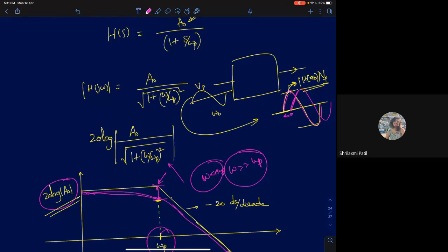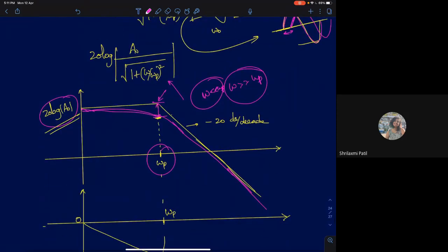And that information about instability, you can understand it by looking at the phase response. So that's where phase response comes in very handy. Magnitude response is very important because that's a fundamental characteristic. You need to know what the range of frequencies is for which your amplifier will give you the gain. Phase response becomes more important or critical, especially for systems when they are put in feedback.